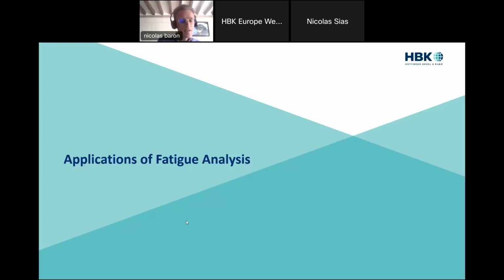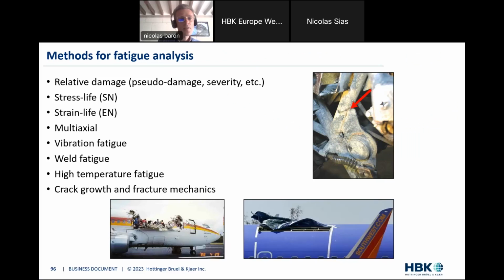Some applications and some examples finally to conclude the seminar before the Q&A session. The methods we have talked about are mainly stress life and strain life. Those are the core methodologies. Now, when you have more specific needs, and typically when you're dealing with multi-axiality, which is a rather complex topic in and of itself, or when you are doing vibration fatigue. Vibration fatigue is a very specific topic, but it's very important in real life: fatigue due to vibration phenomena.